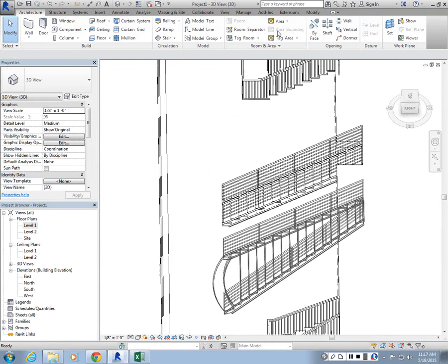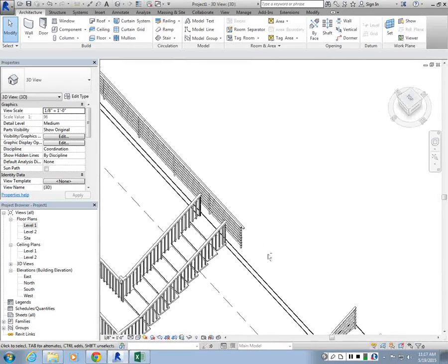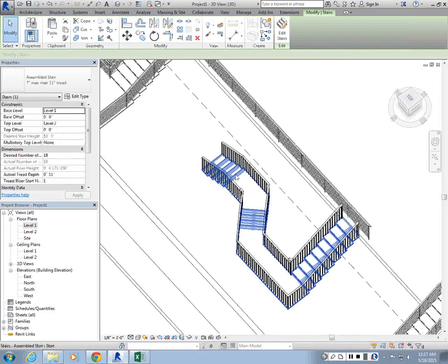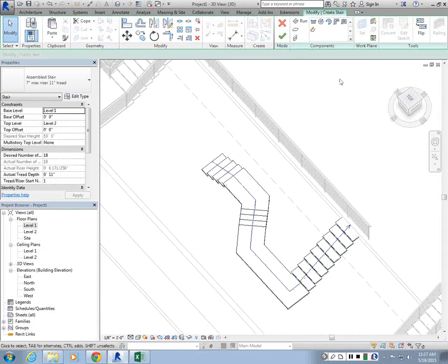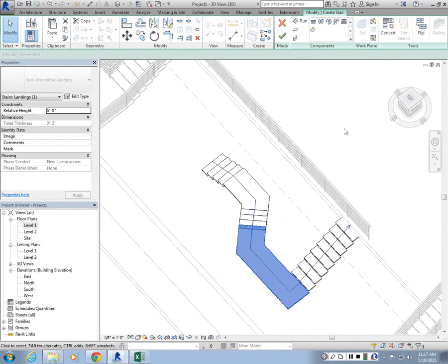Right? So because these are all hosted objects, you can customize them. You can create deconstructed stairs as well. But I would always recommend you to start with an existing one. So like I can also do it to this one. I can choose this one, edit stairs, choose one of the risers and do convert. You can also do the landings as well.